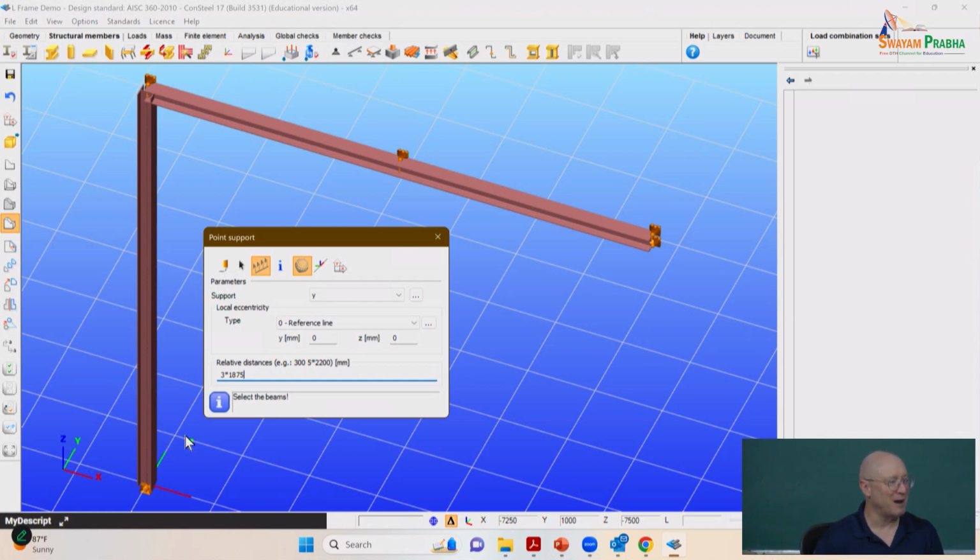So I've already looked at the design of this column, and I need 4 braces out of plane to get it close to working. One at midpoint will not be sufficient. It won't support the load that I'm going to try to put on it.